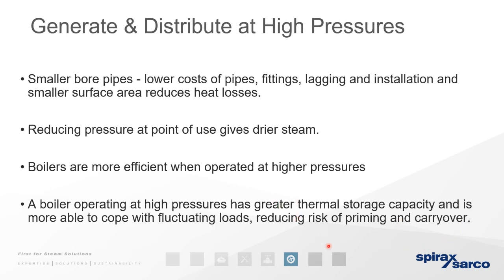Boilers are much more efficient when operating at higher pressures. And then I think the most important point is this one: a boiler operated at high pressures has a greater thermal storage capacity and is much more able to cope with fluctuating loads.